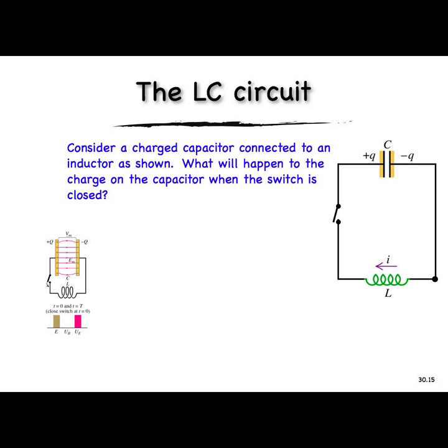We don't see anything very interesting right here. What I'm looking at is the voltage across the switch. So these 2 leads right here go to this box, and then from this box go to the oscilloscope. This box is a voltage divider. It's just a pair of resistors that are set up to reduce the voltage by a factor of 10. So right now, I have 0 voltage going in, 0 voltage coming out. We see a nice 0 line on the oscilloscope.